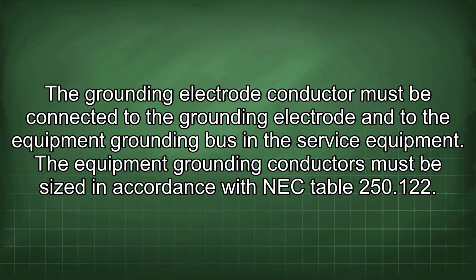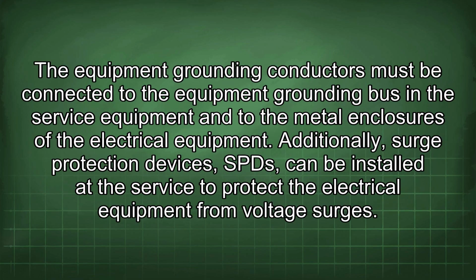The equipment grounding conductors must be sized in accordance with NEC Table 250.122. The equipment grounding conductors must be connected to the equipment grounding bus in the service equipment and to the metal enclosures of the electrical equipment.